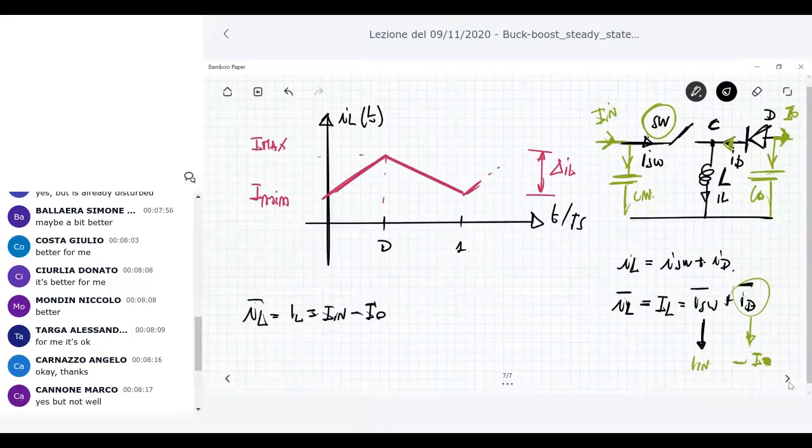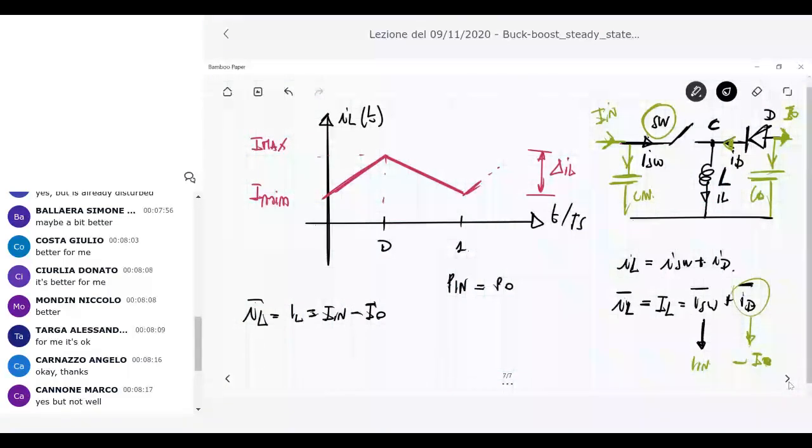So what is the input current? In order to derive the input current as a function of the output current, we can apply the condition that you always have in lossless circuits. My analysis here, as a basic assumption, is a lossless circuit, so we cannot have any energy loss. So the power at the input should always be the power that you dissipate at the output side.